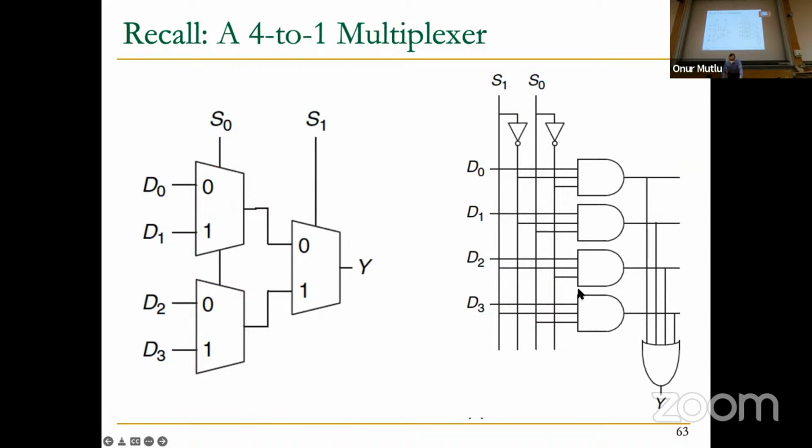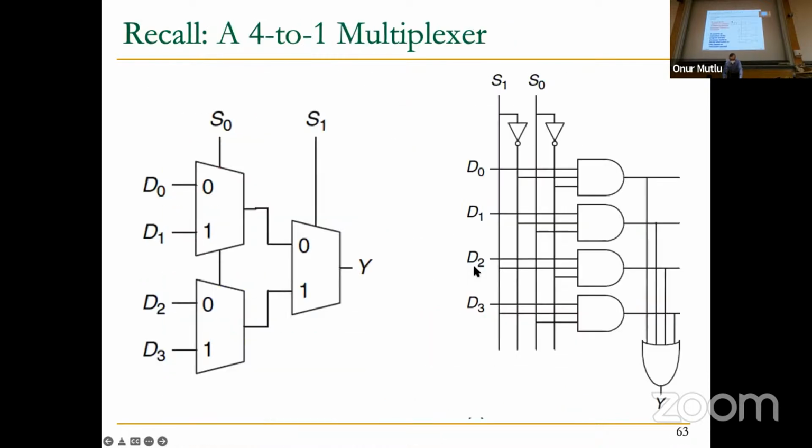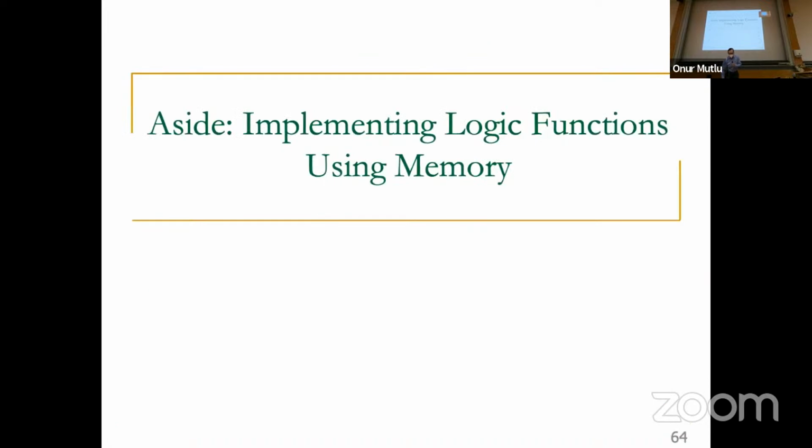Basically, the multiplexer is essentially these purple things over here, plus, of course, these ones over here that are not highlighted. Okay, so this is a 4-to-1 multiplexer. We just used these 2 plus the gated D latch and connected them together to form memory and replicated them to form memory.